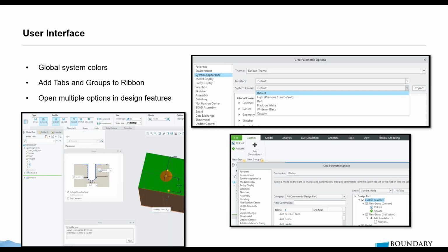I know some of the CAD administrators will copy config files and user interface files over each time the users start up Creo, which means every time you start up Creo, you're going to have the same config files, the same things. So there are tools in the background for CAD administrators, something like the config.sup that we can use, and that will split the scenario a little bit, where CAD administrators can get what they want and users can get what they need to design or to develop their products.